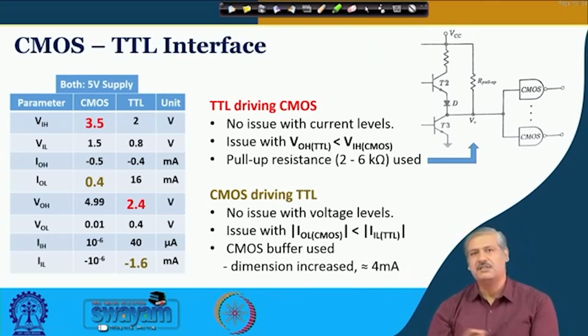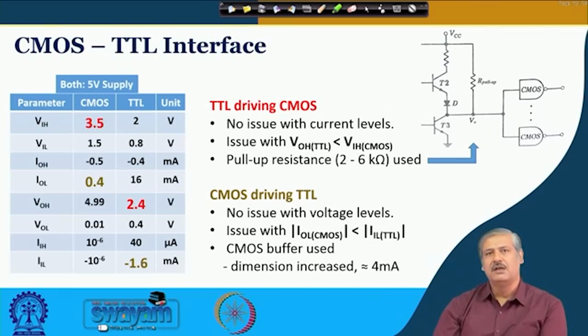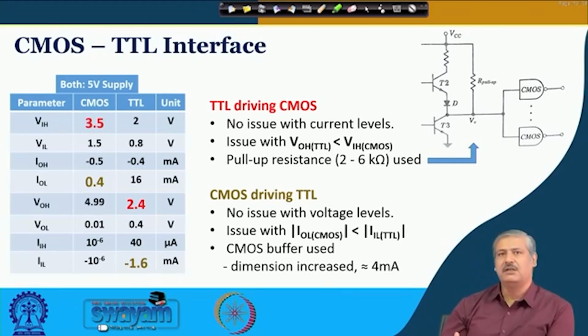Finally, the last part of our discussion, okay, CMOS circuits are there, TTL circuits are there. There could be cases when, for less power consumption and more packing density, we prefer CMOS, right, and for higher speed and associated benefits, we are thinking of using TTL, and then we want to connect these two parts for getting both the benefits.